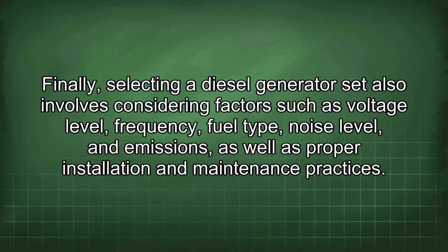Finally, selecting a diesel generator set also involves considering factors such as voltage level, frequency, fuel type, noise level, and emissions, as well as proper installation and maintenance practices.